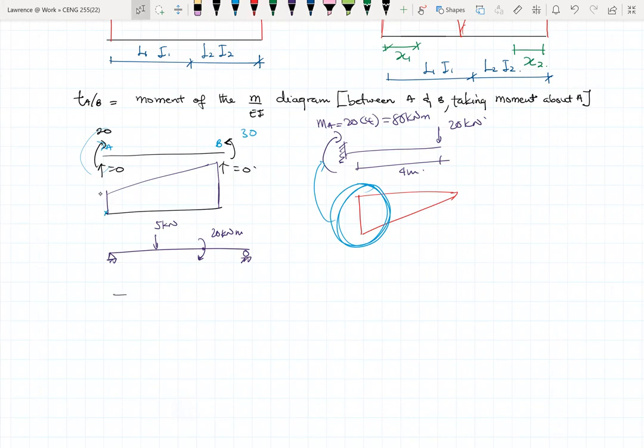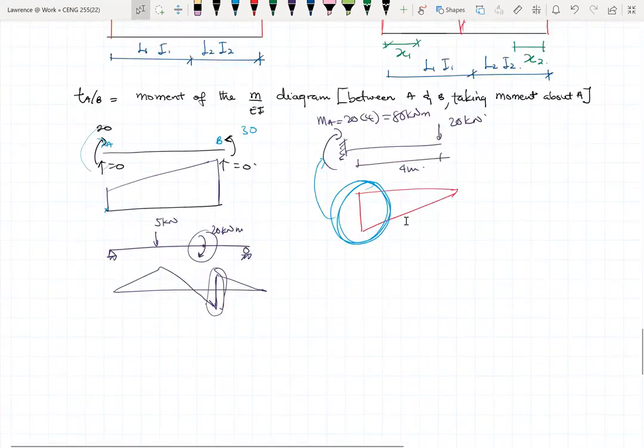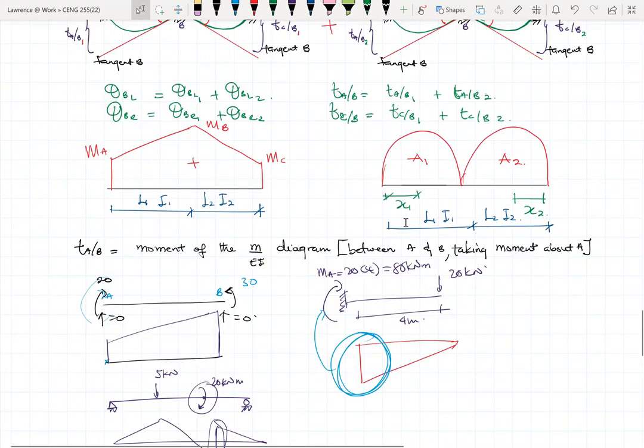Normally, this will be our bending moment diagram for such a case. It might have something like this, because of the point moment there's a vertical jump in the moment. I can explain this further for you. If you want us to have a one hour tutorial session, I can explain further why these things are what they are, because the assumption is that you've done basic structures, so this should be okay for us.